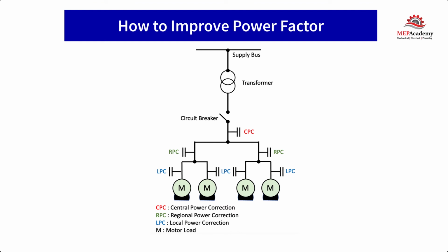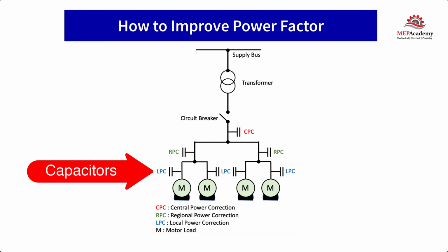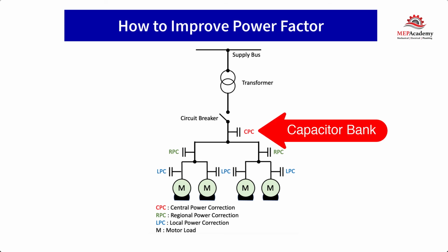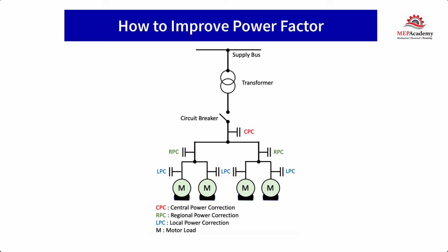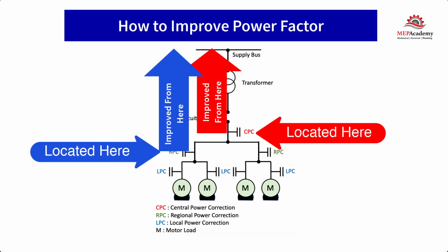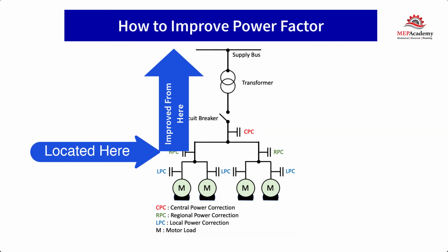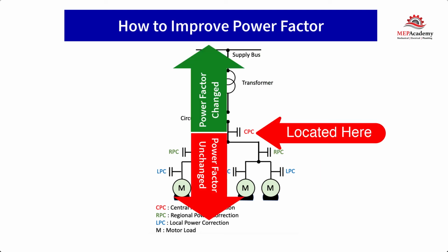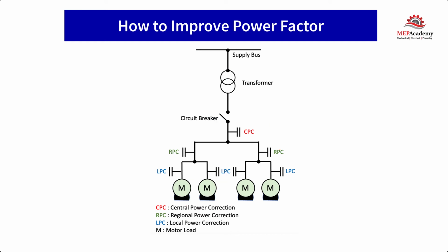Locating the capacitor at the motor corrects any interference coming from the motor. If you have a lot of motors, then you might consider locating the capacitor at the service entrance switchgear to avoid having capacitors all over the facility. Wherever the capacitor is located, it will improve the power factor between that point and the power source. Remember that this means the power factor between the capacitor and the load or motor will remain unchanged. Capacitance causes current to lead voltage, while inductance causes voltage to lead current.